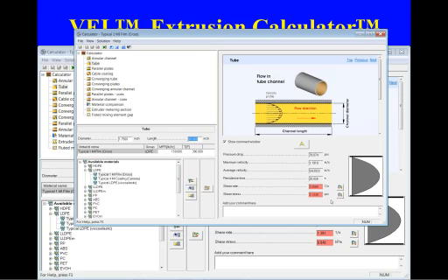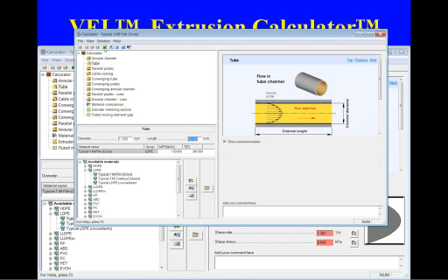And we got tired of this, so we added this nice little button right here. And when you click on this, it automatically changes this to the optimum channel size that avoids the problem with the minimum shear rate and shear stress. Now this is an odd drill size, so we would probably go 1.125, the 1 1/8, for our adapter size.